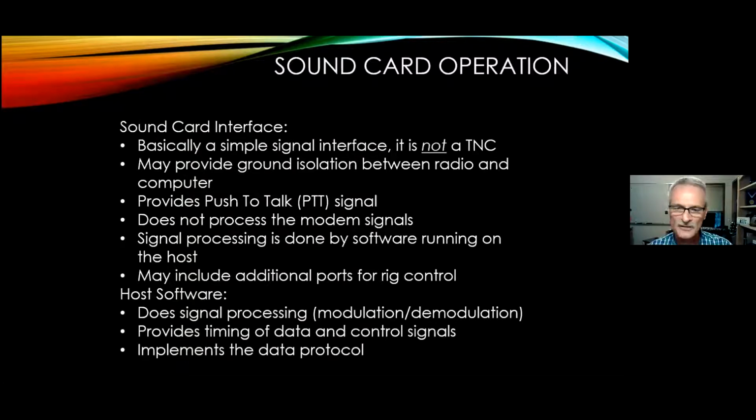It does not process the signals from the radio or the signals that it's sending to the radio. All it does is, it's essentially a digital to analog converter and an analog to digital converter. We send it bits and it turns that into an analog waveform, or it takes an analog waveform and turns it into bits. It has no idea what those bits are and doesn't care, okay? Doesn't know whether it's modem tones for your packet radio or if it's Linda Ronstadt. It doesn't know, doesn't care, just sends it on out.